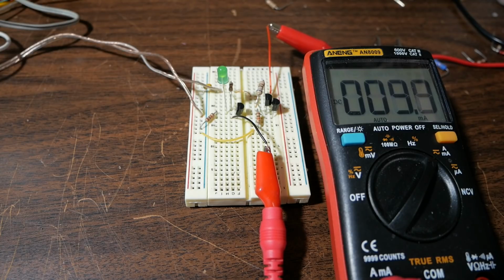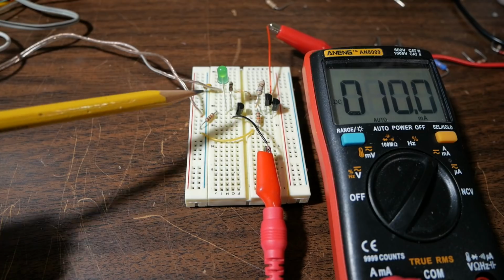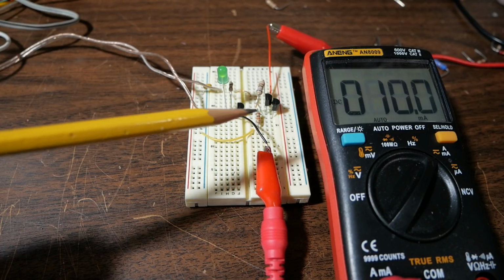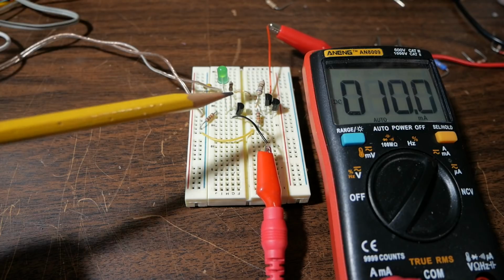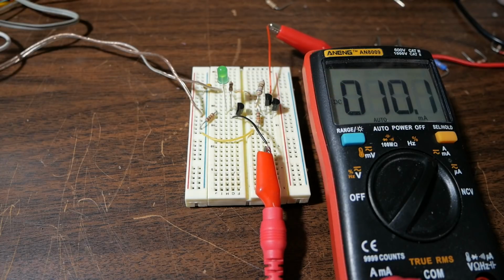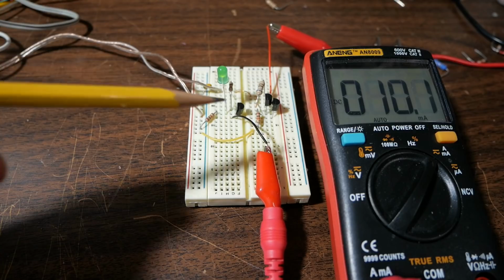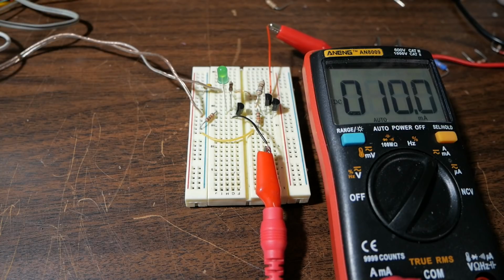1.4. Yeah, around 1.3 or 1.4 volts it seems to be back in regulation. And from about 1.5 volts all the way up to 32 volts there was a change of 1 milliamp. So yeah, for being such a simple circuit, it is doing a pretty good job.